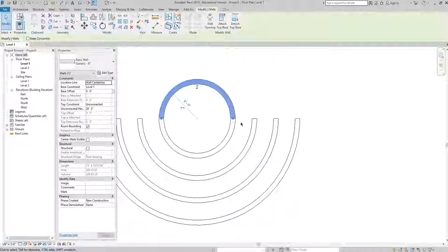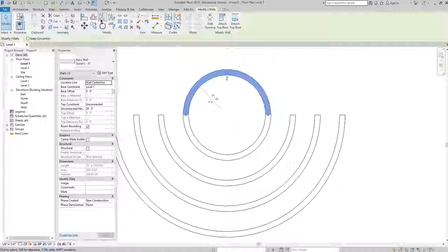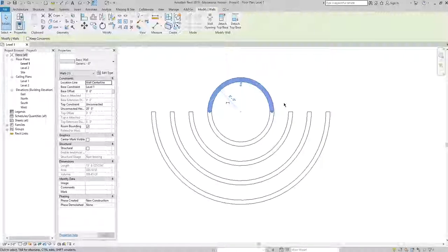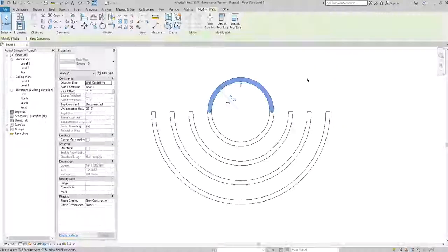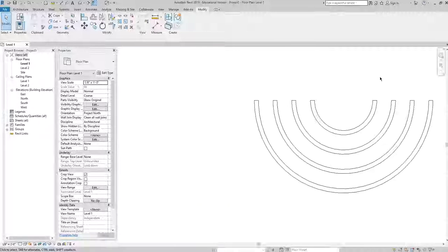Okay. So most of the time, if I'm using a pick, there's an existing element that I want to mirror about, like a wall in between two doors, and I just want to get the same object on the opposite side of the wall. If I'm using a drawn axis, I don't have something in between two objects that I want to mirror, and so I have to draw the axis in order for that second object to mirror about where I want it to go. Sort of makes sense. Any questions so far? Not terrible, right?